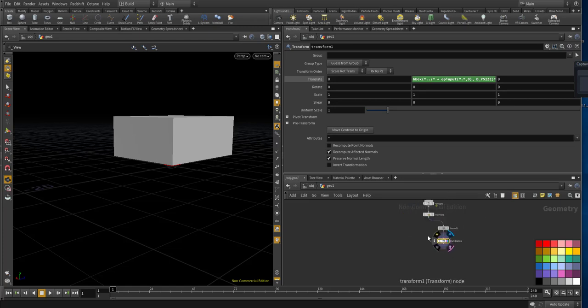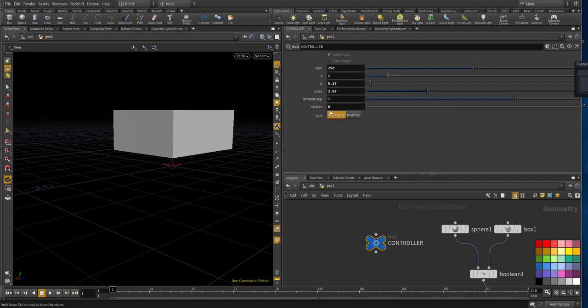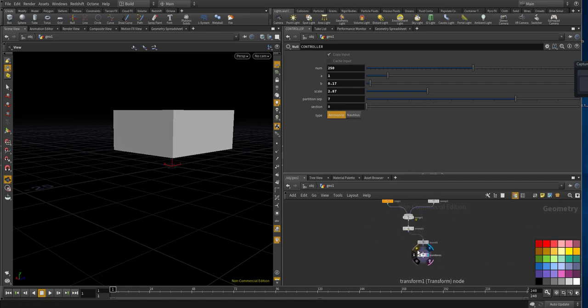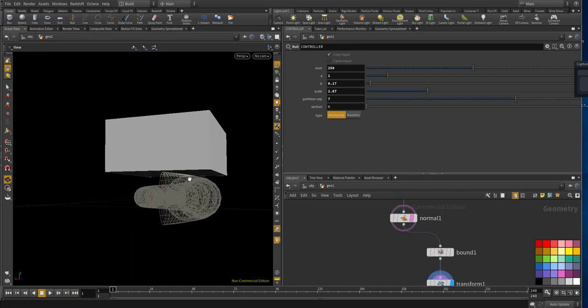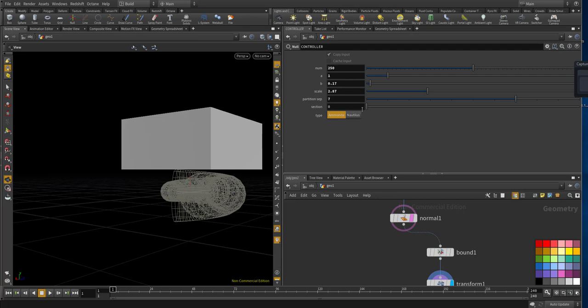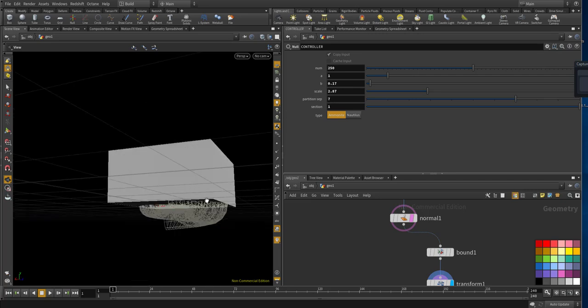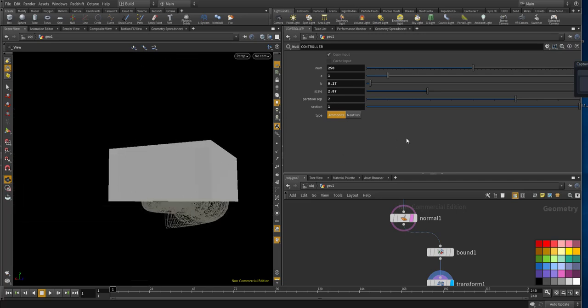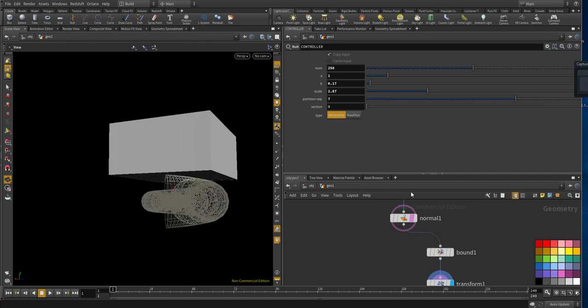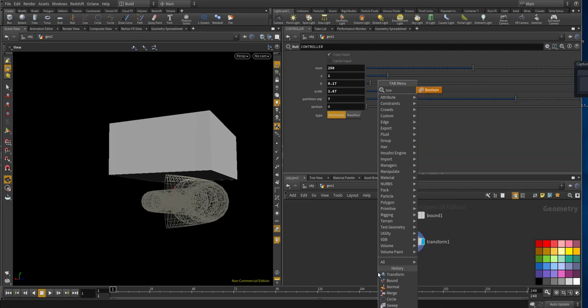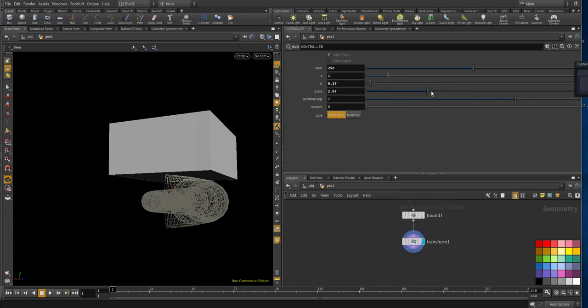So if the section value is 0, it's all the way up, and the geometry is around here, so it's not intersecting. But if I increase the value of the section, if it gets to 1, the Ammonite shell will be chopped in half using this boundary. And in order to chop, you need a boolean, as I used for the partition.